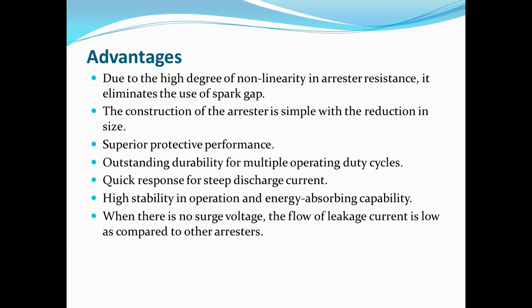We know that if leakage current is there, the temperature of that arrestor increases. So if there is no surge voltage, there is no leakage current, that is, under normal operating conditions.